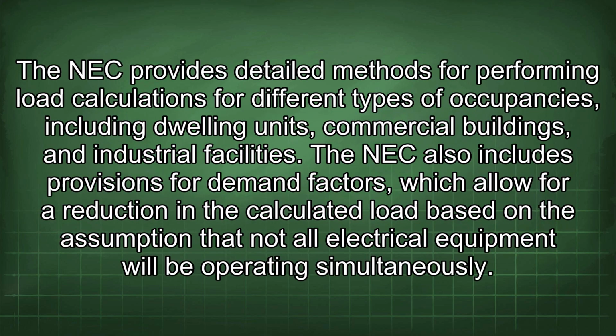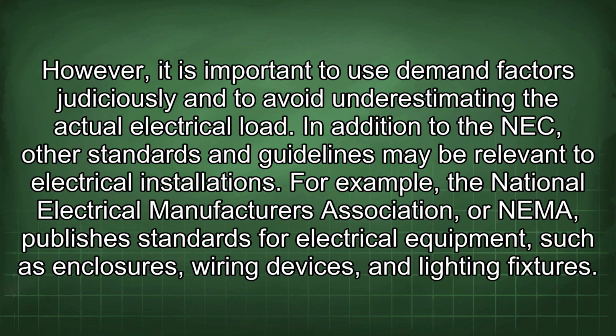The NEC provides detailed methods for performing load calculations for different types of occupancies, including dwelling units, commercial buildings, and industrial facilities. The NEC also includes provisions for demand factors, which allow for a reduction in the calculated load based on the assumption that not all electrical equipment will be operating simultaneously. However, it is important to use demand factors judiciously and to avoid underestimating the actual electrical load.